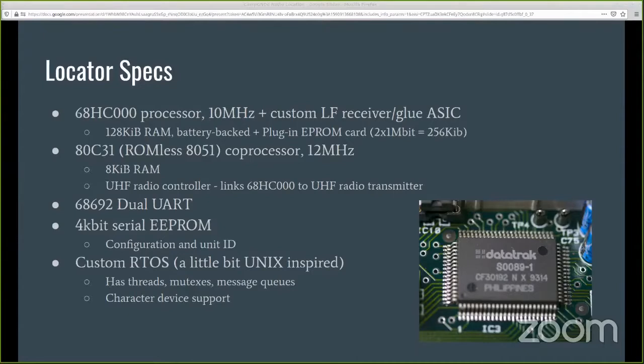So there's an 8-bit latch that the 68K can write to, that the 8051 can read from, and in reverse order there's a port where the 8051 can write and the 68K can read, and there's an interrupt whenever one transmits to the other over that port.